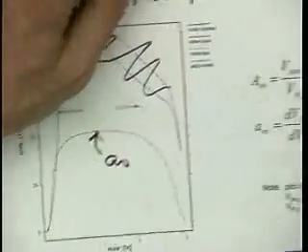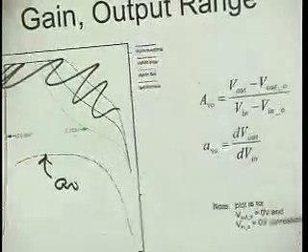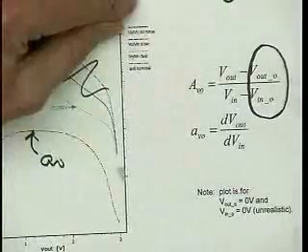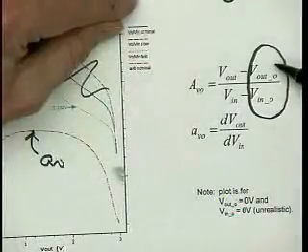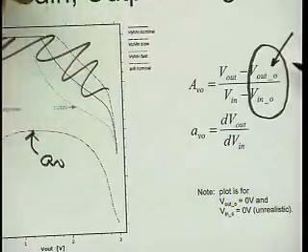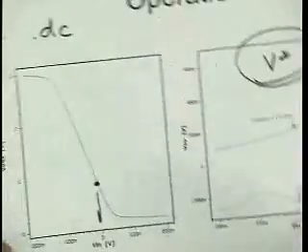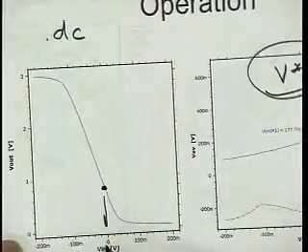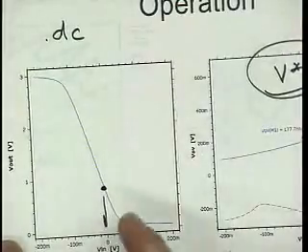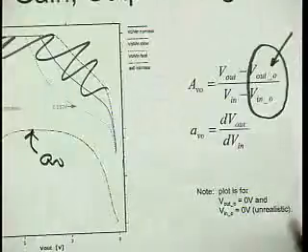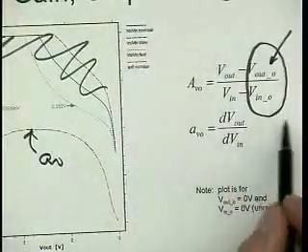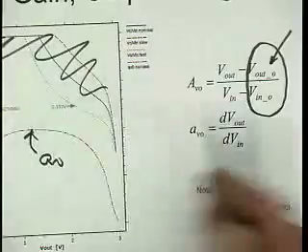Really, what I need to do is use a correct biasing point. And now I've done that for the input, but for the output, I also should have subtracted the voltage that I'm getting when my input is here. But actually here they are identical, right? Because I diode connected it. So I should have also subtracted whatever it is from the output voltage. I didn't do that, and therefore I got this wrong result.